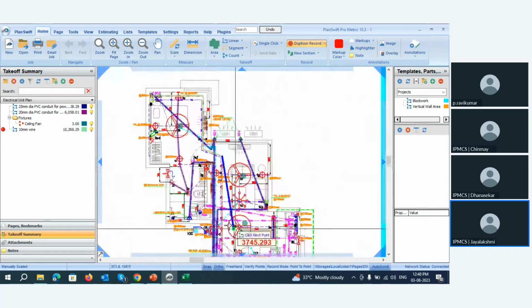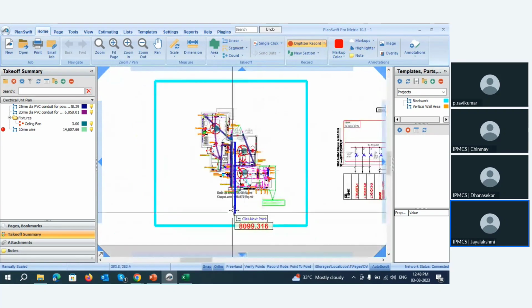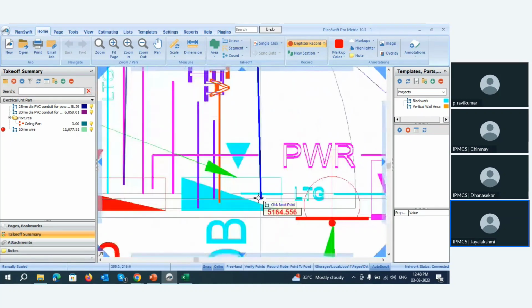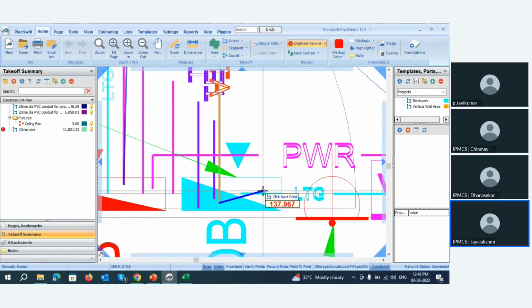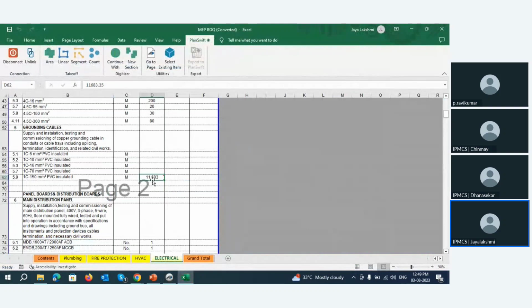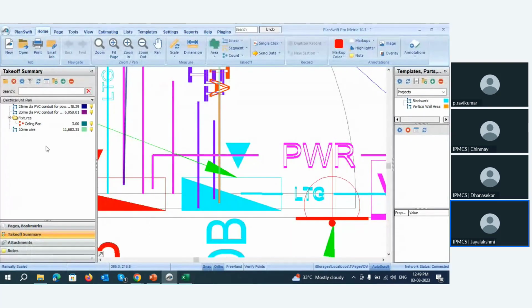And go on by just left clicking. And let me zoom on to this point. Yes, done. Click on escape. And the work is done now. You can see the Excel is getting highlighted now in the bottom, and the measurement is seen here. If you see here, there is a note like item 10 mm wire, properties quantity. You can see that also the same, the 10 mm wire, whose quantity is 11,638 mm.